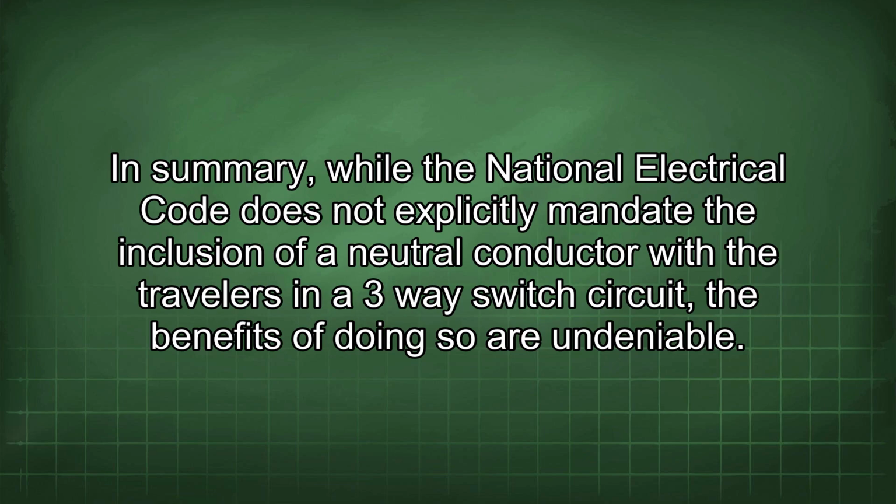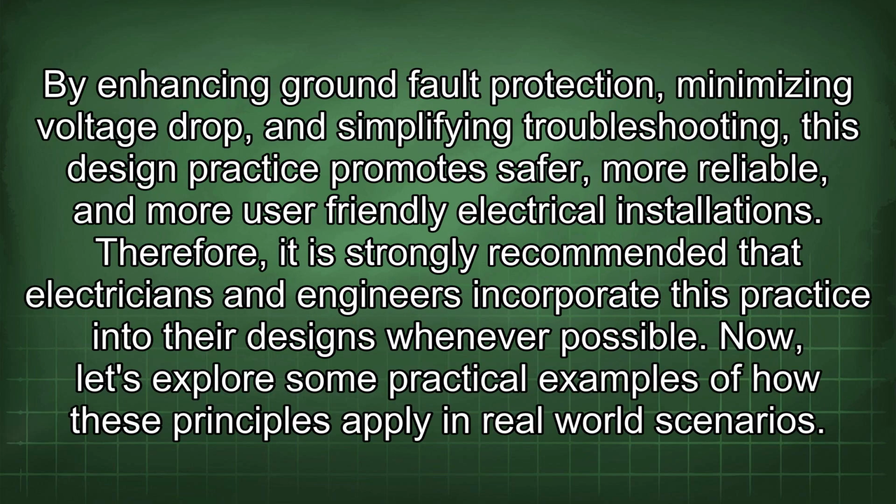In summary, while the National Electrical Code does not explicitly mandate the inclusion of a neutral conductor with the travelers in a three-way switch circuit, the benefits of doing so are undeniable. By enhancing ground fault protection, minimizing voltage drop, and simplifying troubleshooting, this design practice promotes safer, more reliable, and more user-friendly electrical installations. Therefore, it is strongly recommended that electricians and engineers incorporate this practice into their designs whenever possible.